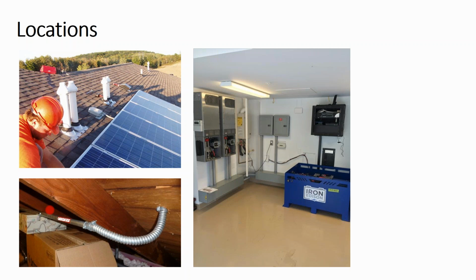So this conduit, if it can be rated for a dry environment all the way up to that penetration point, but that's assuming that you're sealing the conduit. And so you might find yourself doing an install. We recently did one where it was a standing seam metal roof, and there's a roof cap that goes across the roof and a little 1-inch gap in that roof cap. This was a metal roof, so we didn't want to drill through our metal rooftop. We also didn't want the conduit to run across the roof. And so we said, well, can we go into the roof cap and run our conduits down through the roof cap? The answer is yes.